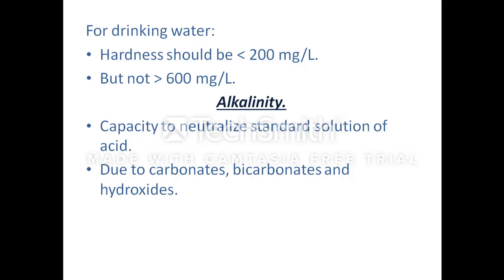Now coming on to the alkalinity. It is the capacity to neutralize the standard solution of acid. It is due to the presence of bicarbonates, carbonates, and hydroxides. Maximum alkalinity is caused due to bicarbonates. The bicarbonate alkalinity and hydroxide alkalinity are never present in the same water sample. So the total alkalinity can be either equal to carbonate alkalinity and bicarbonate alkalinity or carbonate and hydroxide alkalinity.